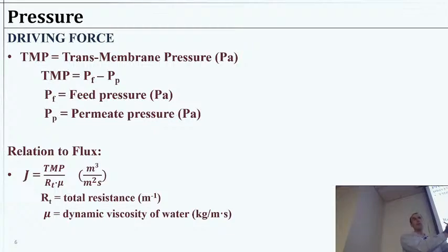So the feed has, let's say, 1,000 kilopascals, or whatever pressure unit you want, and then 900 kilopascals in the permeate, so it was only a 10% pressure drop, so that the remaining pressure can drive another membrane that requires more pressure. So you could set these up sequentially, and any given membrane can probably only handle a certain level of pressure differential. That would be the deal.